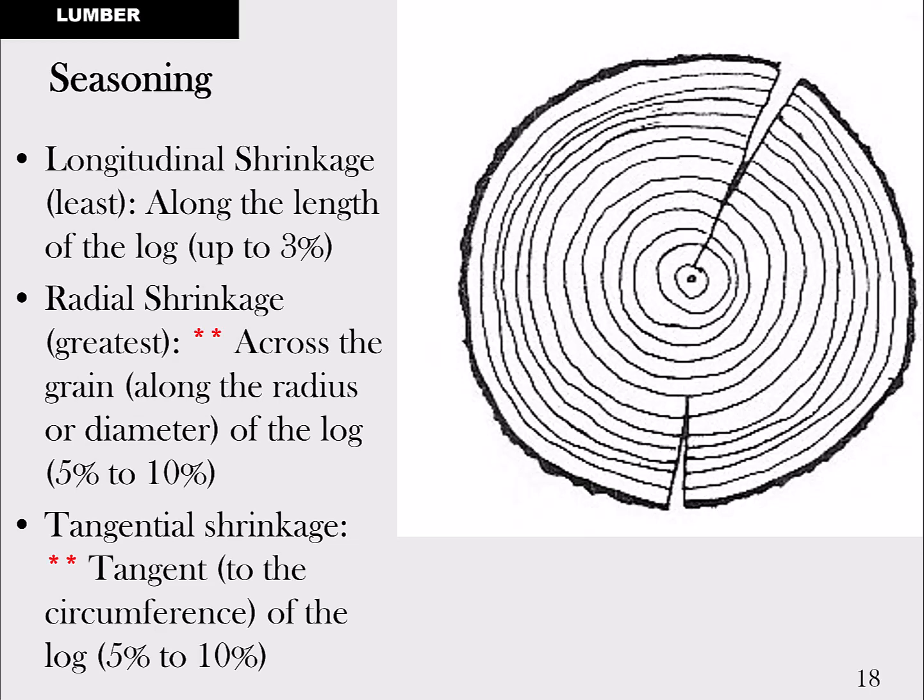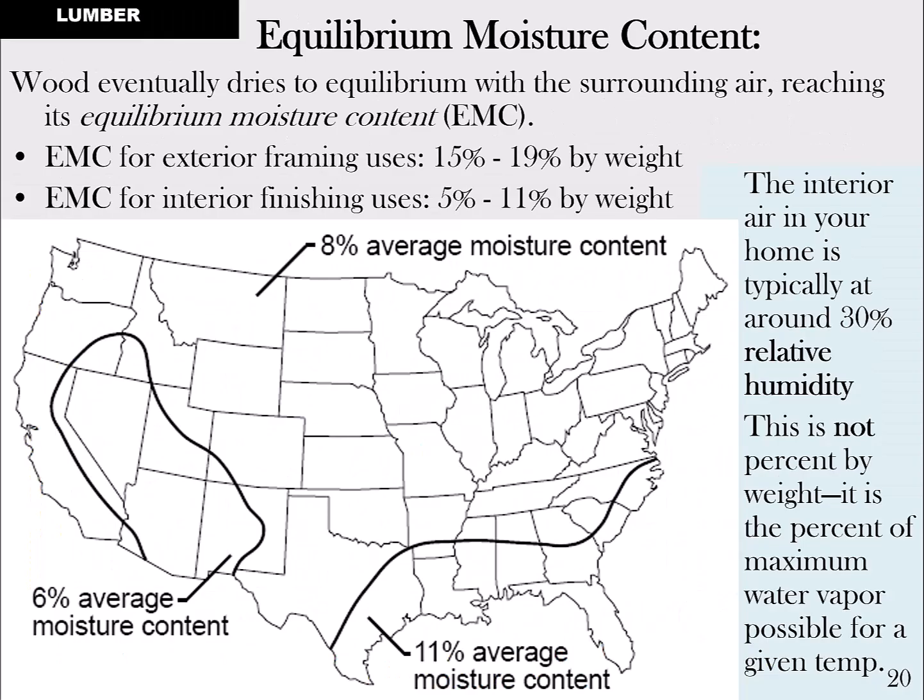But okay, so equilibrium moisture content is another thing. EMC, or equilibrium moisture content. Over time, I kind of alluded to it a few moments ago, where you get the lumber cured or seasoned down to 15% moisture content, but over time it'll dry out even more depending on the humidity that's in the air. So as you see in the Louisiana area here, we're sitting somewhere around 11 or 12. It depends, but 11 or 12% moisture content maybe.